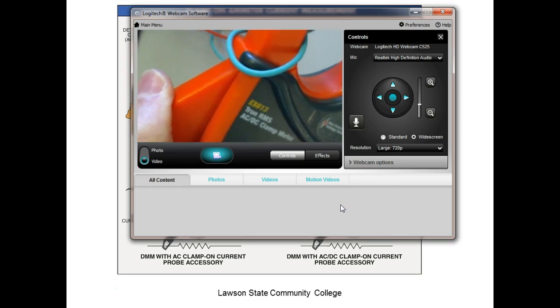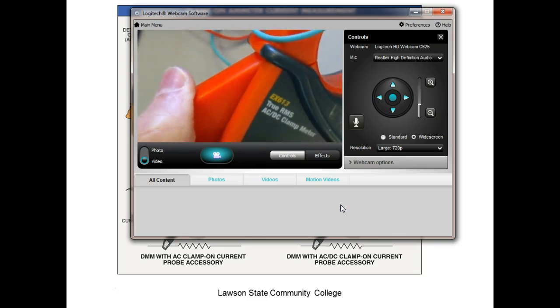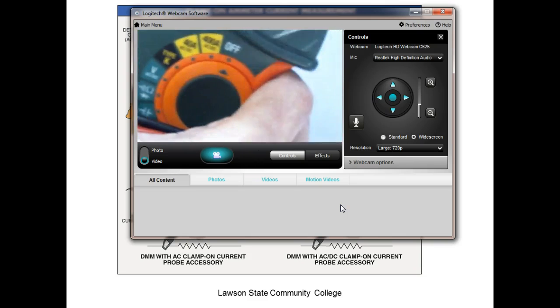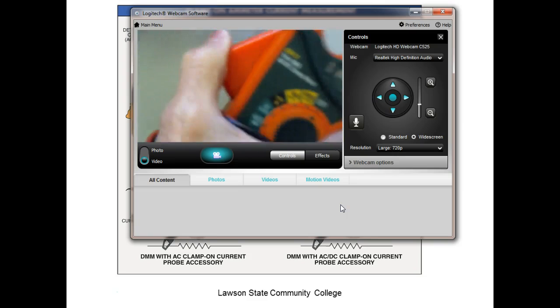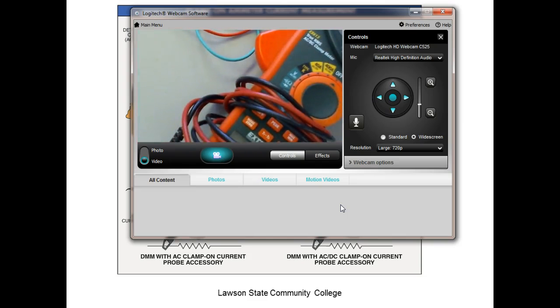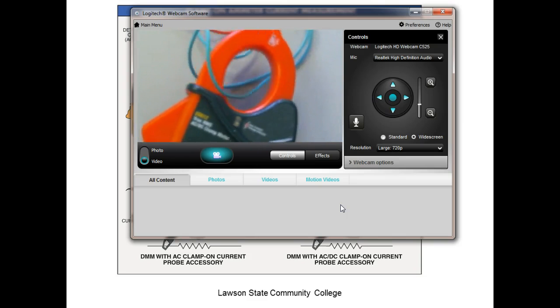So if it measured 2 amps, it would actually be 1 amp. It's just divided by the number of loops. So if you looped it through 3 times, then you just divide your reading by 3, right? Does that make sense? Just divide it by the number of loops, because every time you put a loop, those magnetic fields are going to combine inside that winding. A lot of times that'll allow you to use a clamp-on ammeter in applications that are below what you'd normally be able to measure. Of course, I couldn't use this in any circuit that we deal with here.